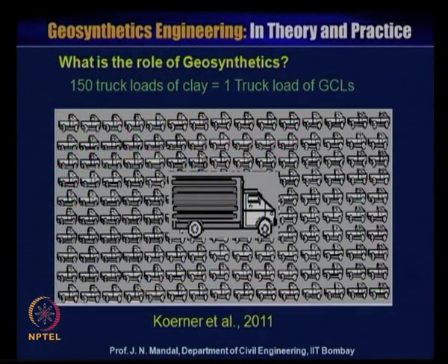We are trying to address one example, like the landfill. For example, when you are constructing a landfill with a compacted clay liner whose thickness varies from 600 millimeter to 1200 millimeter, you require a huge quantity of clay to be compacted.